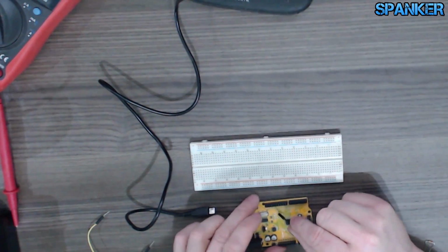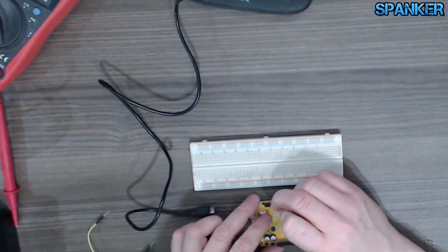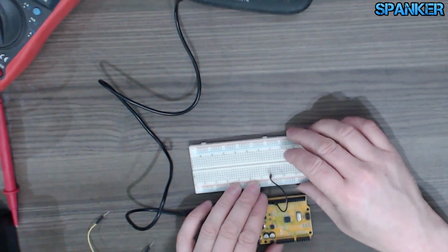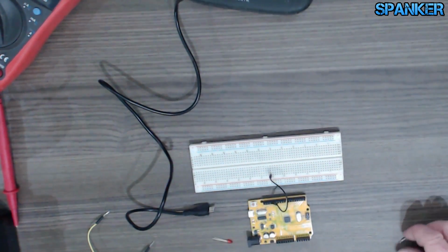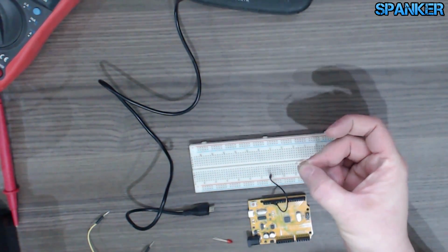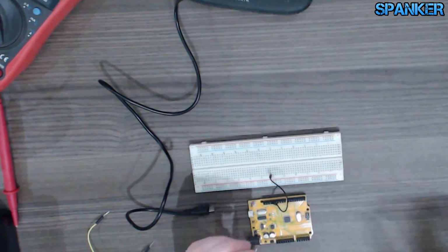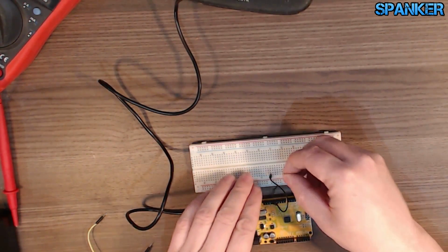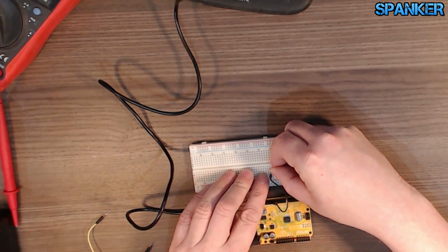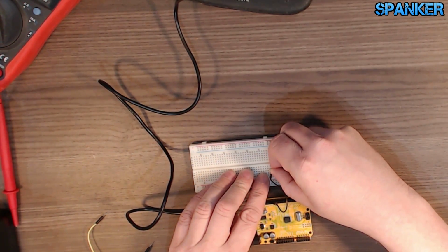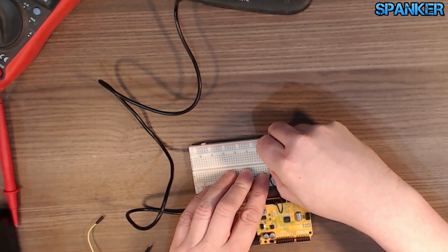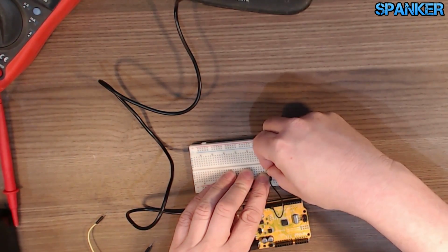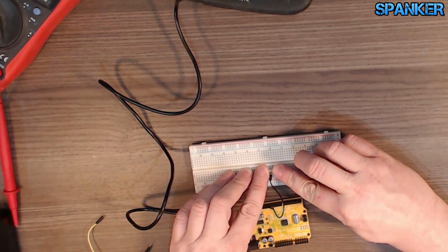We're going to find pin 13, which is this one, and plug pin 13 into there. And we're going to drop it onto the breadboard. There. We've got a resistor. I think it's a 220. I'll turn the lights on, that might be a bit better. I think it's 220. And on that same track that the output's on, I'm going to put one leg of the resistor in. We're going to go into a slot which is 2 up.